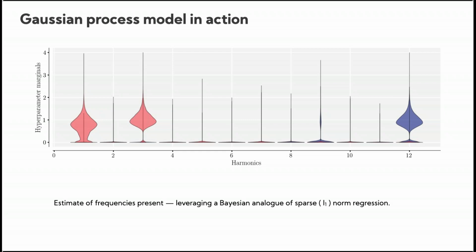As an example, if you were to take a temperature measurement in relatively high Mach number flow, just in isolation, with a single temperature probe, the sources of uncertainty range from recovery, the fact that there are some convection losses between the true stagnation temperature and what's actually measured at the probe head. Depending on the temperature, of course, there might be uncertainties associated with conduction and radiation.